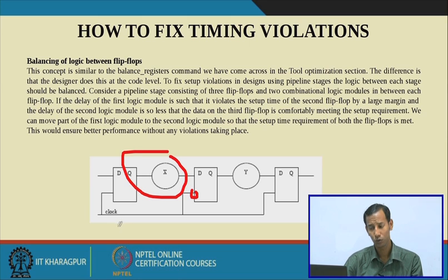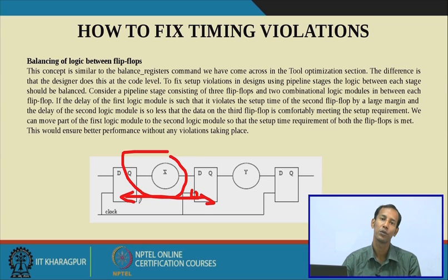To synchronize these two flip flops is very much complicated. You need much knowledge to balance or synchronize these two flip flops running on two different clocks, so that you don't get any kind of violation, whether setup time violation or hold time violation. So we are not covering clock domain crossing here.